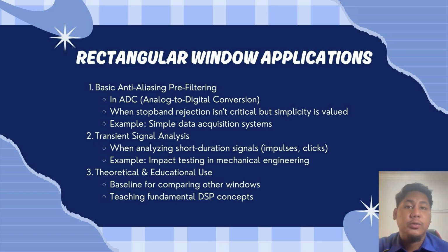Theoretical and education use. Most importantly, rectangular windows are foundational for DSP education. Every engineer learns about spectral leakage and the Gibbs phenomenon first with rectangular windows because they clearly demonstrate these fundamental concepts. They serve as the baseline against which all other windows are compared.